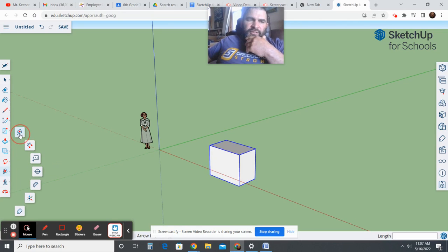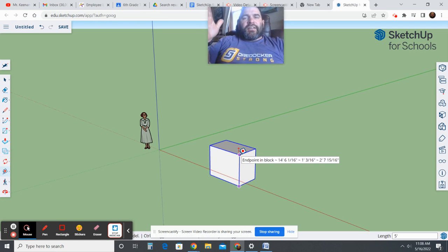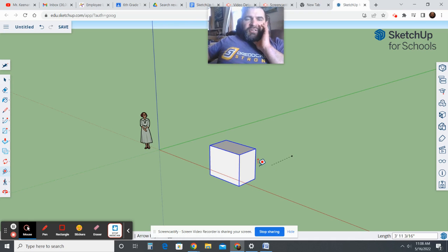You click on the measurement, make sure you have your first defaulted one. You're going to click once on one location, move it down, and you click again, and then the length will appear on the bottom as you go there. You can use this to set lines. You can use this to set offsets. So let's say I wanted to make a parallel line with this edge. I can click twice, and I can use this to set offsets, just like that. I just clicked 4 different times. I clicked 1, 2, and then moved it down, clicked 3, 4, and I made an offset line that's parallel to the top edge of what I just did.